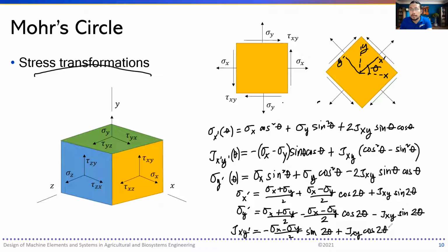And what are the implications of this one? These are actually used to compute for the more critical stresses called the principal stresses, or the maximum in-plane shear stress. Based on these formulae, the principal stresses and the maximum in-plane shear stress can be determined, particularly if a certain material is experiencing shear and normal stresses combined.